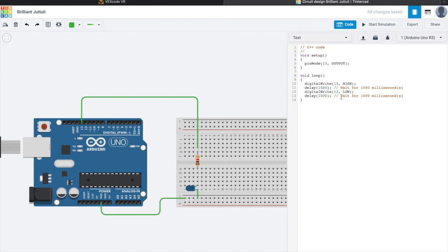You saw a while ago that our LED is actually turning on and off. It's because there is a default program already, and there are two parts of an Arduino program. We have the void setup and void loop. Under void setup, this is where you put all your initializations, your variables, something like that. Under void loop, this is where you put your main code. Okay, this is where you put the operations that you want your Arduino microcontroller board to perform later on.